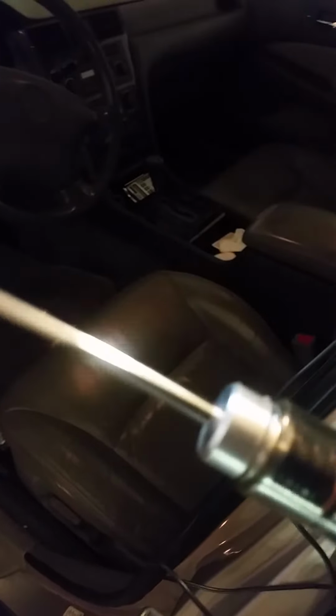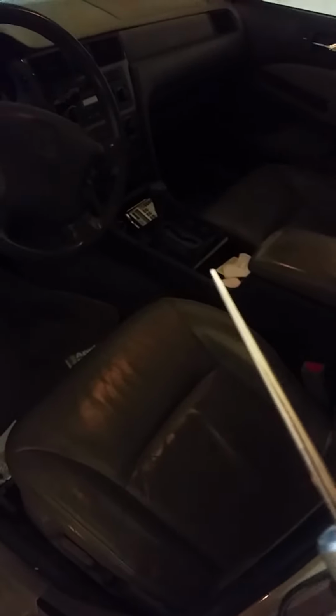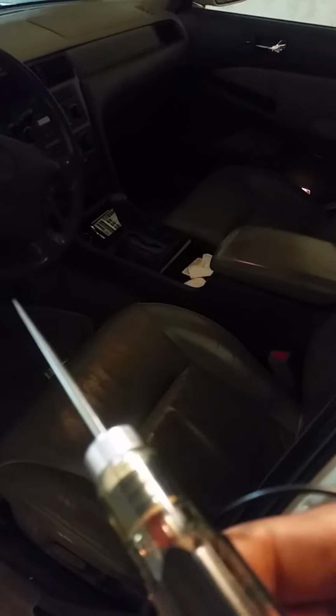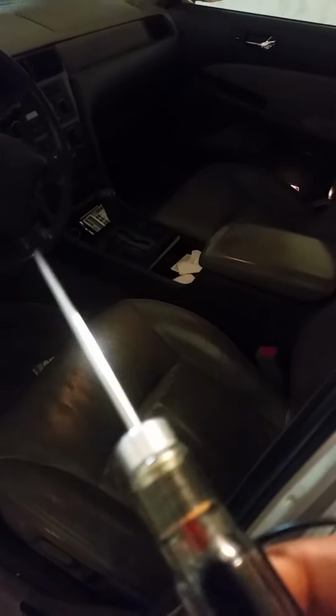I will say this about my test light. It's an LED test light, and there are pros and cons to using this. One of the definite cons is, unlike halogen test lights, if you connect this backwards and you do not pay attention to the test you were doing and what tool you were using, you will continue to misdiagnose the problem because LEDs are diodes.